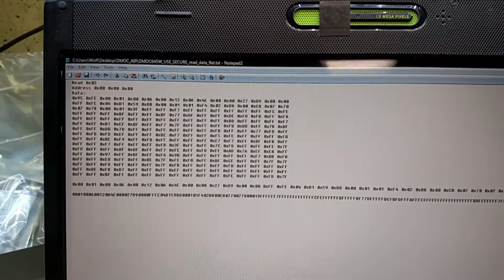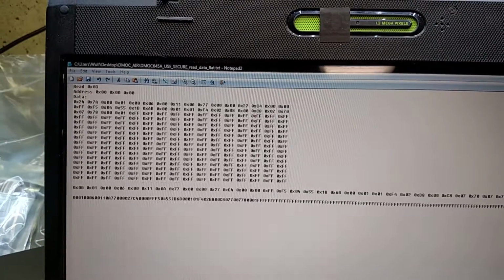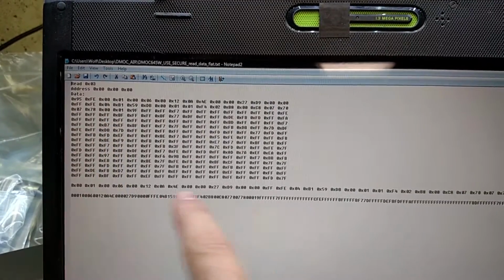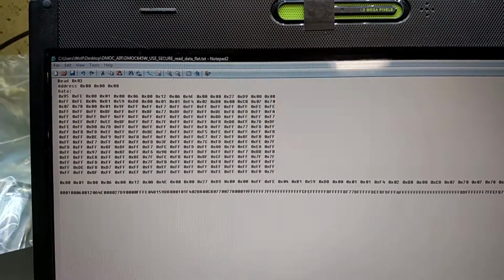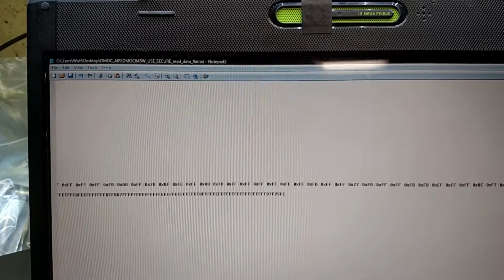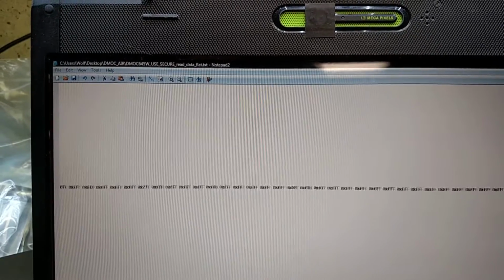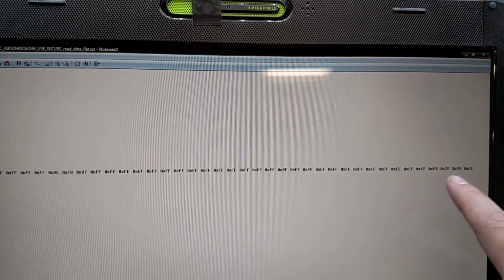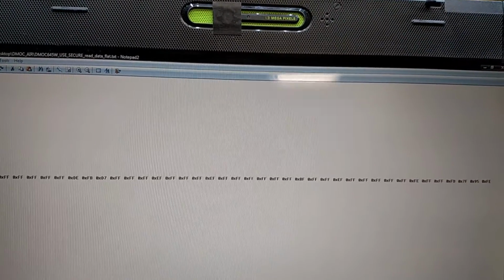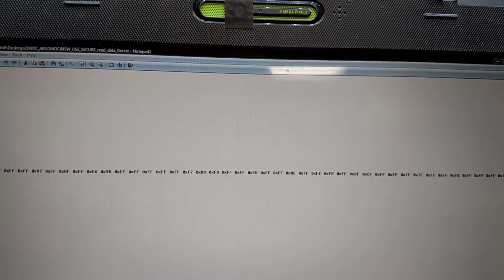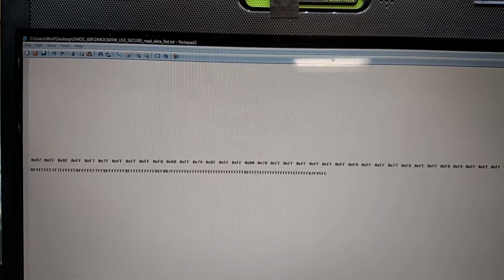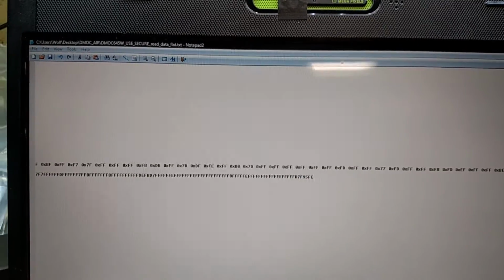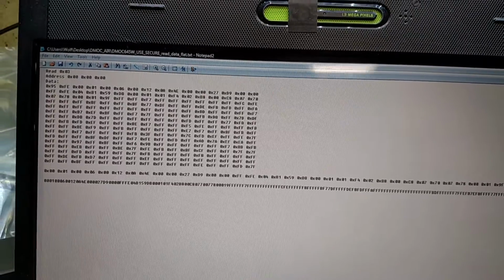So what I've done is I've essentially broken it out into a flat file. I've gone in, the checksum, I put it at the end, so it's just one giant long string. So I've got one with the 0x in front of it, and it just keeps on going and going and going. So the checksum's all the way at the end now, where it normally would be for the programs that I'm going to use. And if we go all the way back here, same with this. This is the same stuff, same data, it just doesn't have the 0x's in there to designate hex.